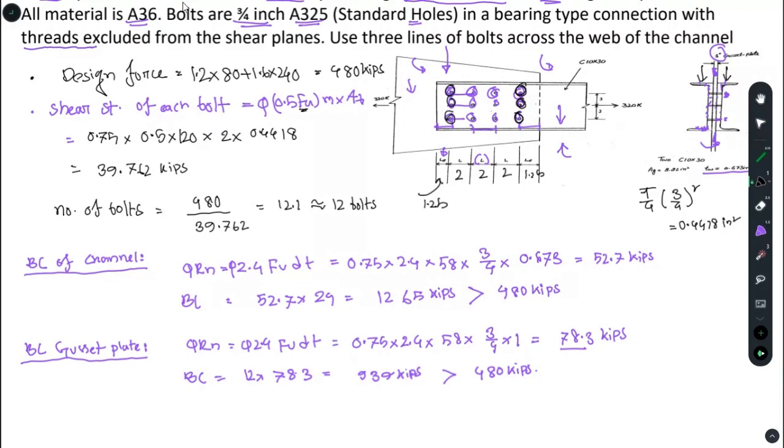Yeah, that is 6 edge bolts, but for these 3 edge bolts right over here, you have a continued section, so these are not actually edged, so it will have, I think, full capacity. So you need not consider 6 edge bolts, you just consider 3 edge bolts, I guess. I don't know the detailed thing, but we consider 3 edge bolts, and the bolts will have a spacing like that, and the number of bolts would be 12.